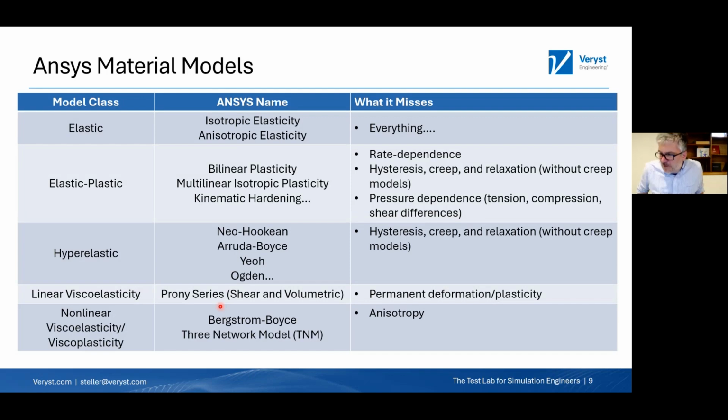Someone asked, where do 3D printed polymers sit? I think that the same discussion just applies. We have anisotropy, so you might have to do a trade-off between, can I get the complex nonlinearities and the complex time dependence with these models, but I can't get the anisotropy. I can get the anisotropy here, but I'm not going to get that complex time dependence or cyclic loading. So sometimes it's a little bit of a trade-off.